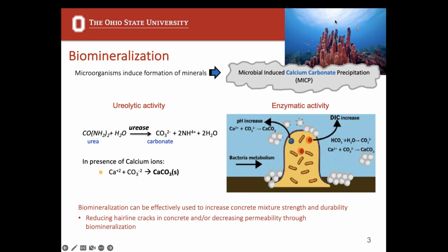So first, a little bit about biomineralization. So this is a natural process. If you've heard of people taking biomimetic approaches to different science ideas, there's some of this going on in structural engineering, there's some going on in additive manufacturing and 3D printing kinds of fields. And we're using that same principle here to help densify and heal our concrete. Microbial induced calcium carbonate precipitation, or MICP, which is also in kind of shorthand referred to as biomineralization, is something that's done, and you can see it happening in corals.